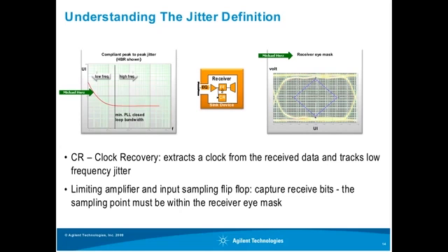So you may wonder, this is less than 1 UI. Actually, you see on the x-axis there's exactly 1 UI, 1 unit interval, and this is the amplitude. And you see in this diagram, in the higher frequency range, this aligns well with the eye mask, but in the lower frequency range, there's more jitter, and this is actually the 1 UI curve here, and it goes even above 1 UI. So how do these 2 graphs match in the specification?